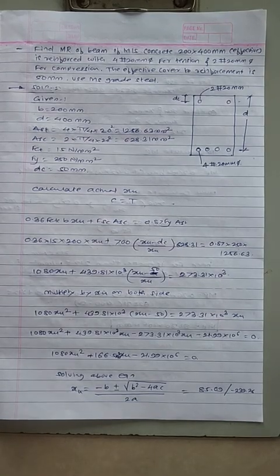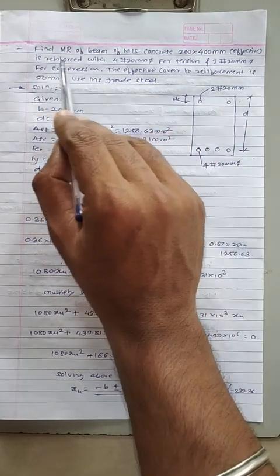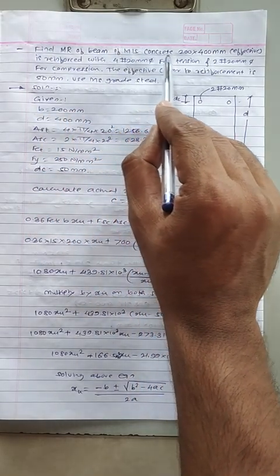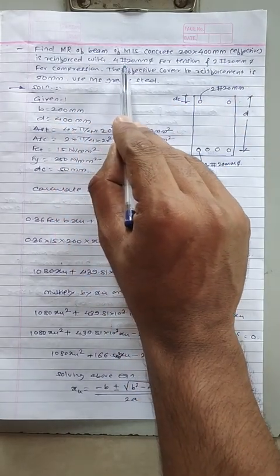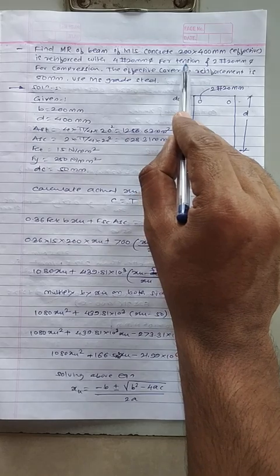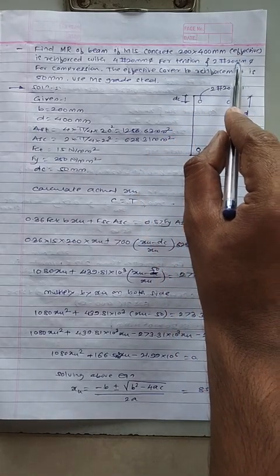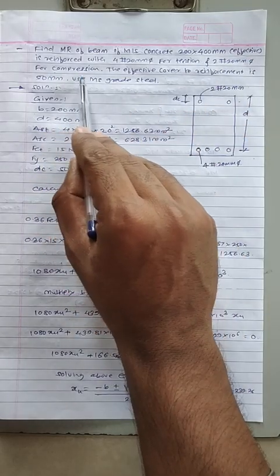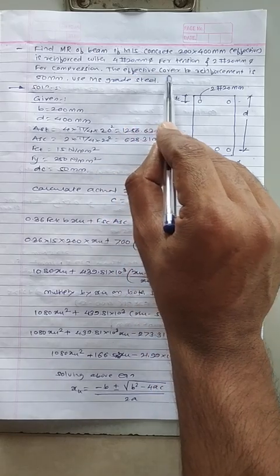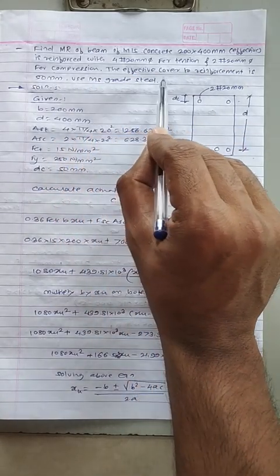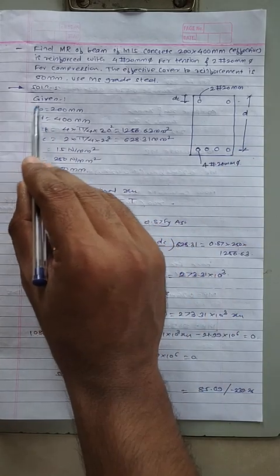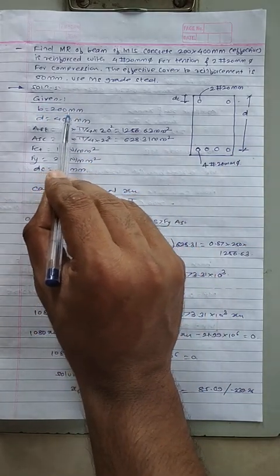Let us see one example to calculate MR of a doubly reinforced section. Find MR of a beam of M15 concrete, 200 by 400 mm effective, reinforced with 4 bars of 20 mm phi for the tension side and 2 bars of 20 mm phi for the compression side. The effective cover to reinforcement is 50 mm. Use mild steel grade. So first of all, write down the given: width of the beam is equal to 200 mm,